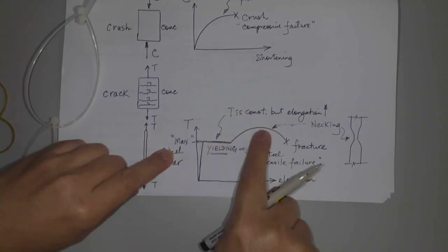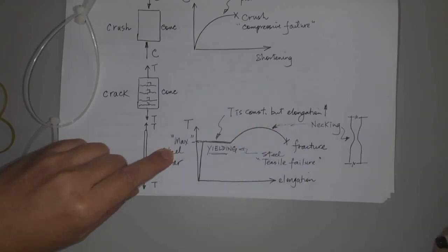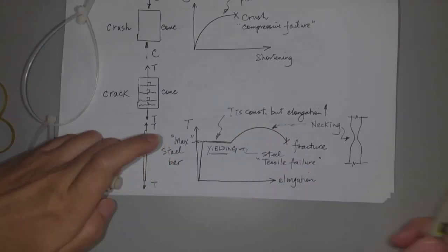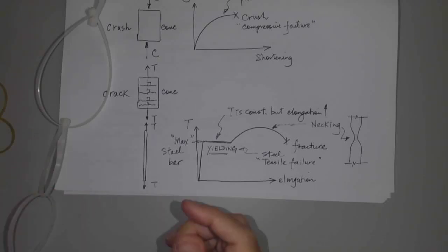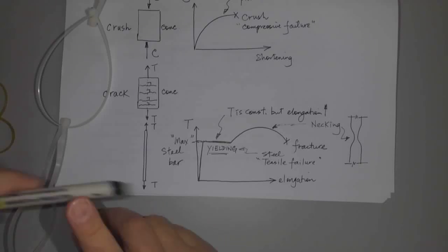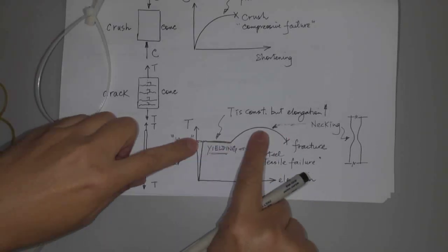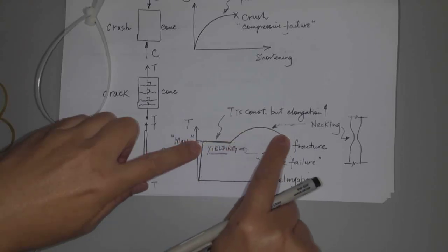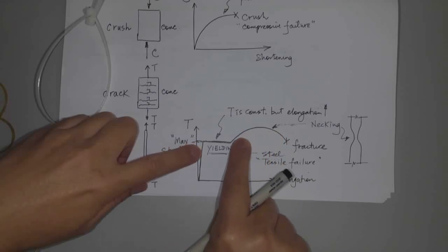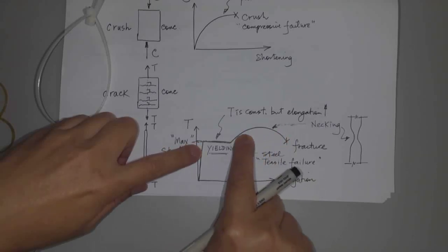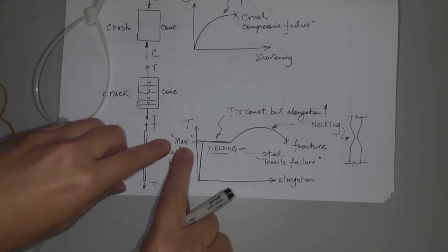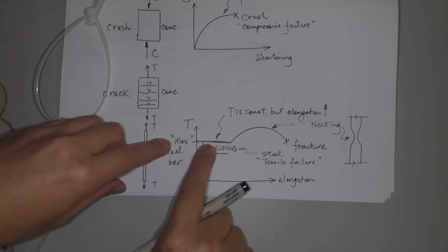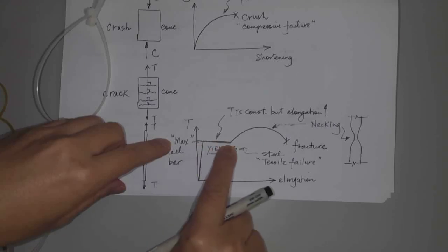And we forget about this region. Okay, so we don't want to see your reinforcement going into this region. If the reinforcement force is going into this region, that's close to the collapse of your structure. Okay, and we don't want to see that. So that's why we define this one as the maximum load that your reinforcement can take.